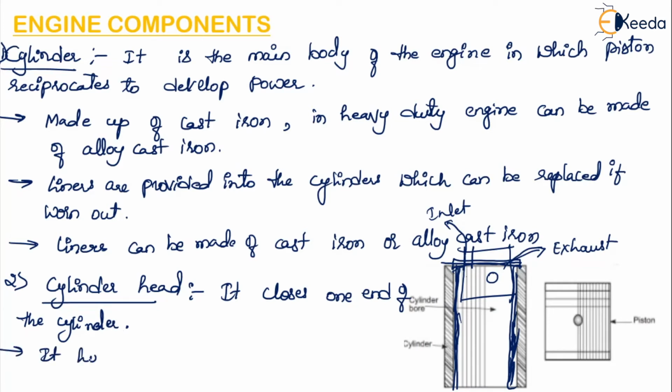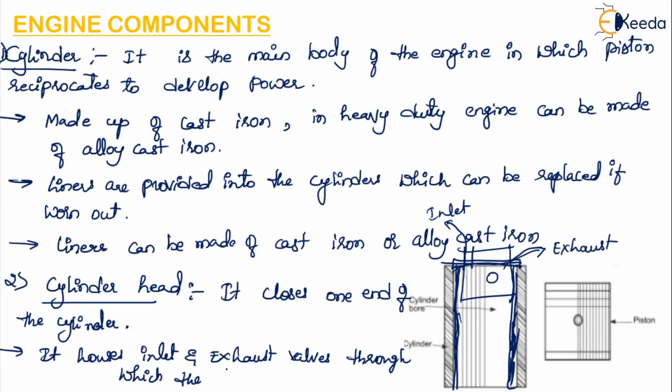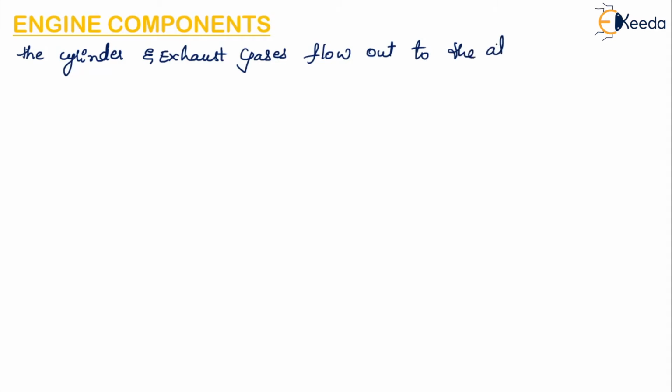It houses, that is, it consists of inlet and exhaust valve through which the charge is taken inside, that is the air and fuel mixture is called as the charge, inside the cylinder, and exhaust gases flow out to the atmosphere from the cylinder.